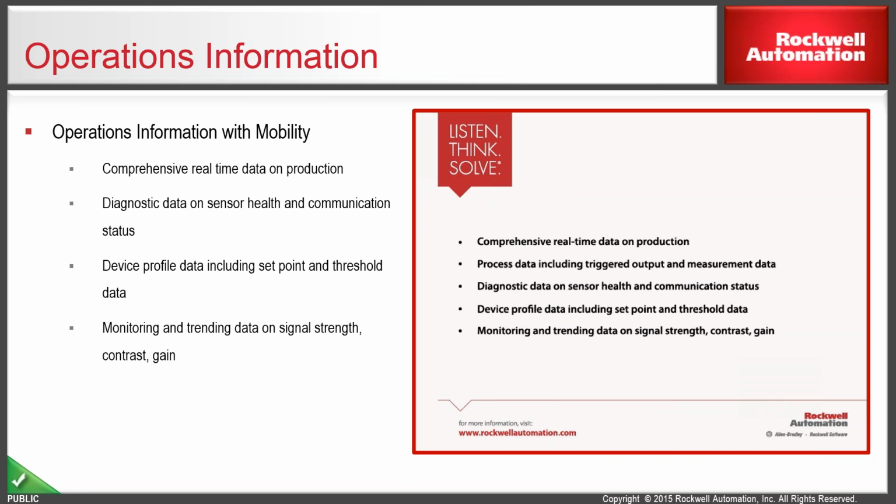This animation was an example of a photoelectric sensor that was implemented in a line. As you know, sensors degrade over a period of time. In this particular example, there was an accumulation of dust or dirt on that sensor. All the sensors installed in that line are tracked using that mobility device, which shows the set point of the sensors and the location of the sensors.